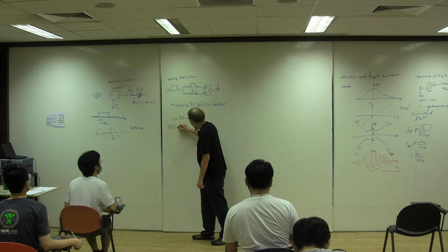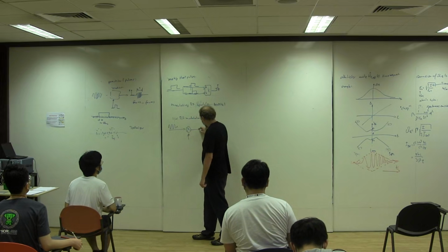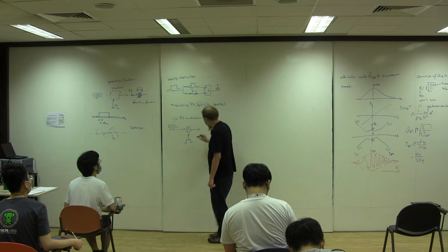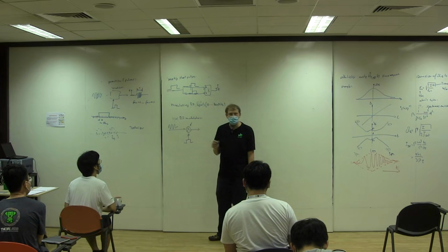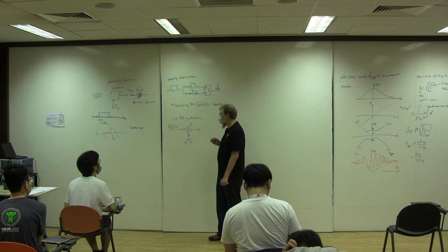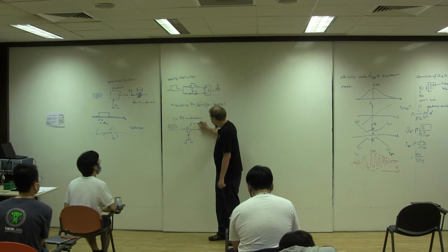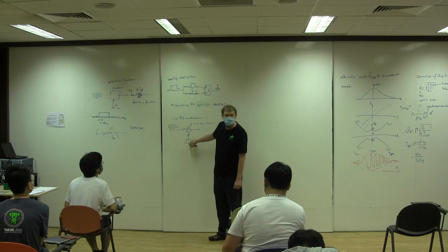So you have your radio frequency input signal, and this basically multiplies an electrical signal with your pulse waveform. This is called a modulator, or since this is just a multiplication, you would find that a normal mixer can also work. Anything that multiplies one field with another field, and that's typically what mixers do.